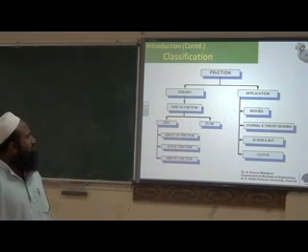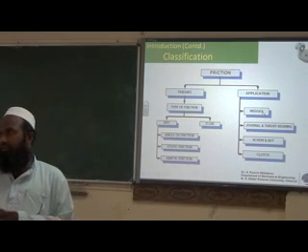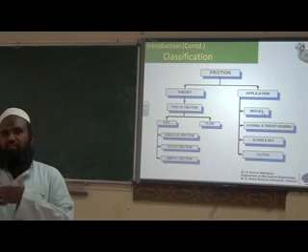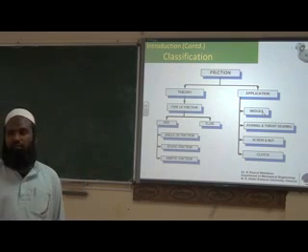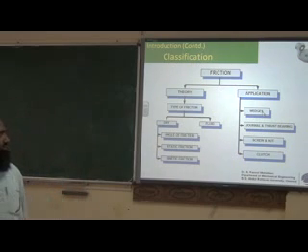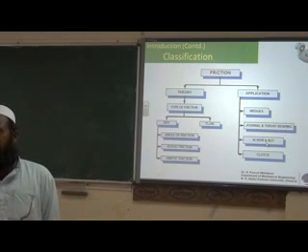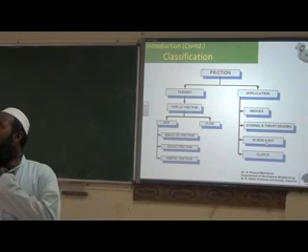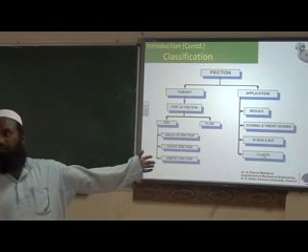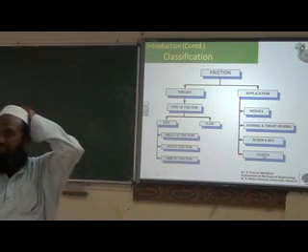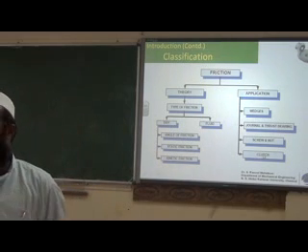And where we apply friction, like wedges, if two wedges are in contact, like the camshaft with a lobe. Okay, there is a wedge, so it pushes the rod. The follower may be a knife edge, which will be a wedge. Similarly, journal bearings and thrust bearings, screw and nut, bolt and nuts, they are also working on the friction principle. Then we have a clutch; the automobile clutch also works on the friction principle. So where we apply friction, we introduce friction.